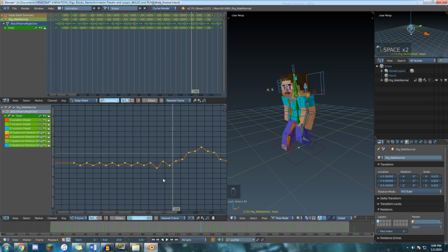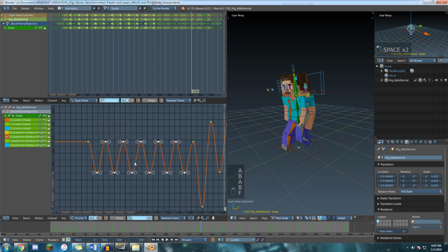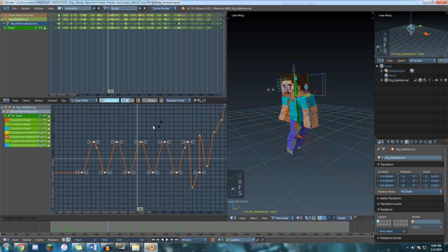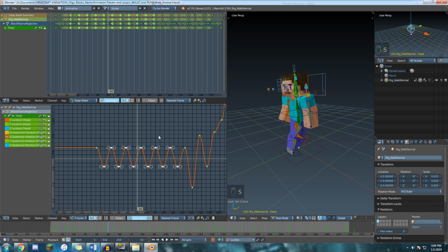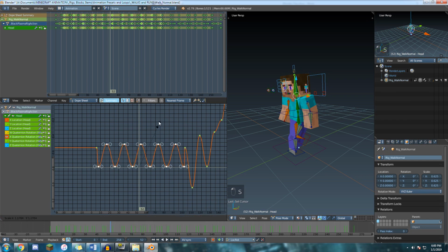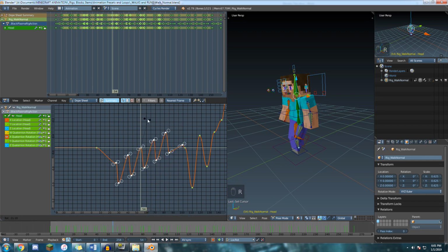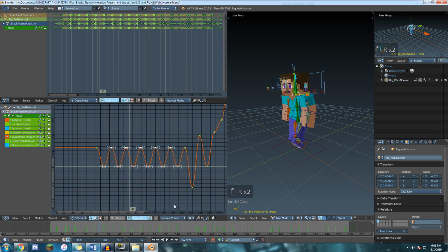There are also 3 different pivot points we can use in here. The default is, of course, the box select, which means if I want to scale these, it will scale everything around the middle. I can constrain that to scale Y, around the Y, but it's still scaling right around the center point. I can change that to something like the cursor. Now I can move the cursor and it will scale around where the cursor is, which is useful if you want to leave one side alone, but scale the other side. Everything still rotates around wherever your point is.